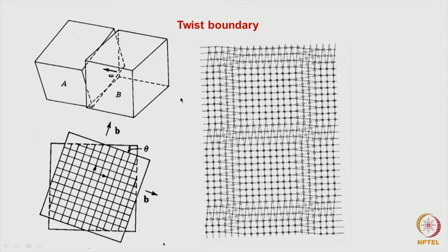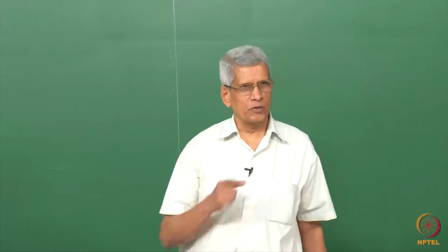If some dislocations are generated in this region, perfect matching could be there in the region in between. By having these dislocations, we could stabilize this boundary while still maintaining the small twist. Generally, these dislocations are screw-type dislocations, which always give rise to a twist.